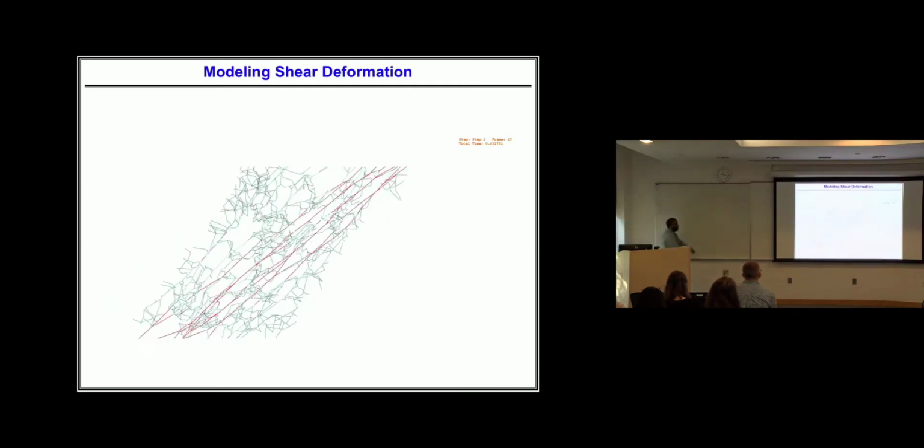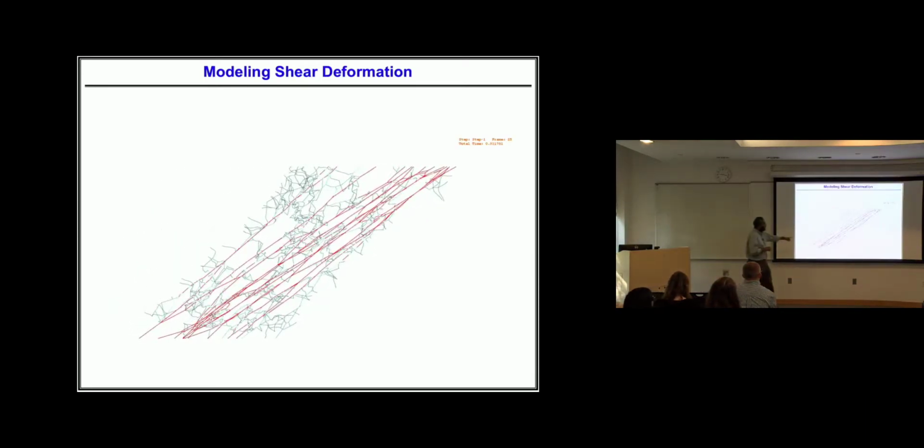So you see now when you deform this material, a lot of these fibers that were perpendicular to the direction where there is high tension, so I'm shearing this material. As I'm shearing this material, what's happening is the fibers in the 45-degree direction all stretched, and the ones in the perpendicular direction actually buckled, okay? And so there is this phenomenon that actually gives it the nonlinear character.